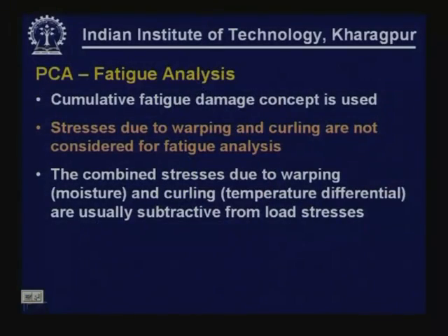carrying out fatigue analysis. The combined stresses due to warping, which occurs because of variation in moisture within the slab, and curling, which occurs because of the variation in temperature within the slab, are usually subtractive from load stresses most of the time.